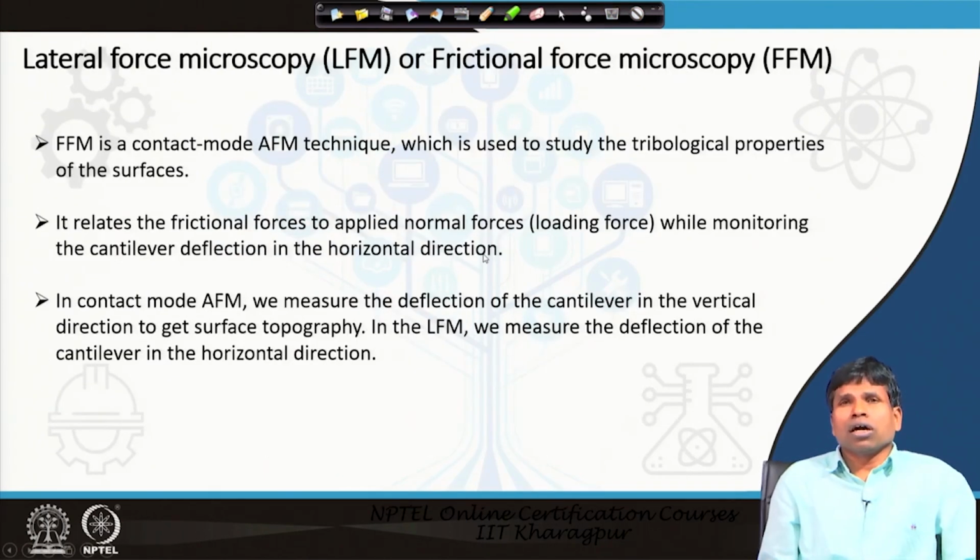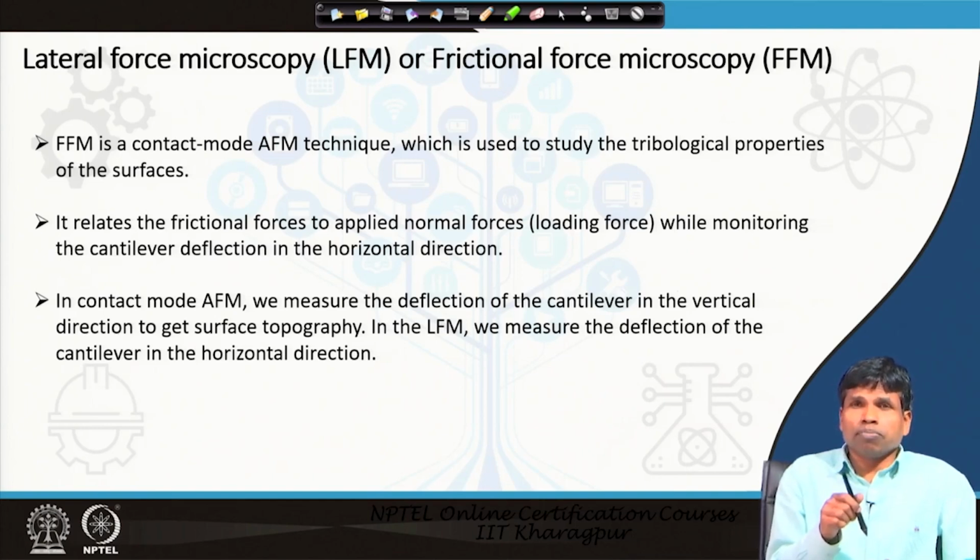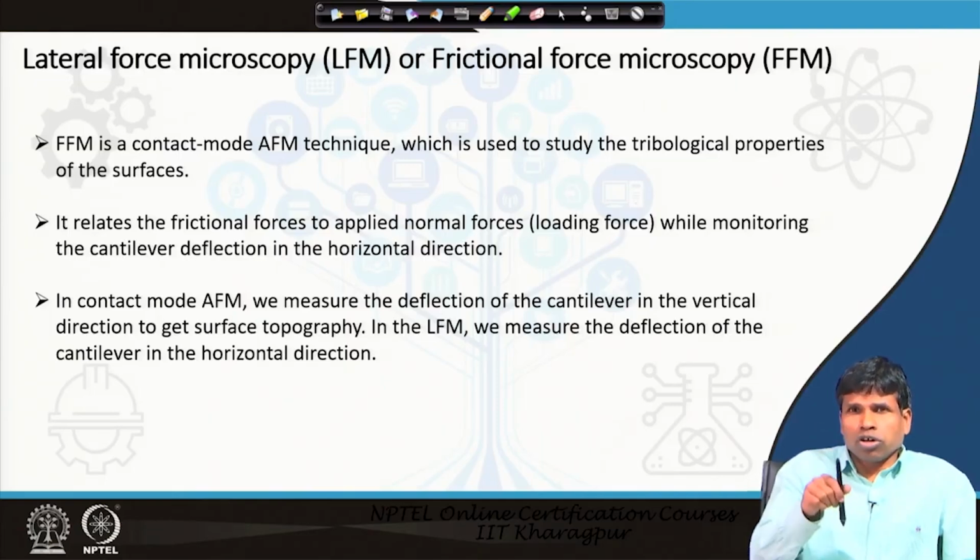Then another important microscopic technique is the lateral force microscopy or frictional force microscopy, or FFM or LFM. This is a contact mode technique, that means the tip must be in contact with the sample, and it is used to study the tribological properties of the surface. And the frictional force is related to the loading force. Loading force we apply vertically on the sample through the tip, and then we are putting a force vertically in the z direction, but due to the lateral force of the sample, the tip may bend,